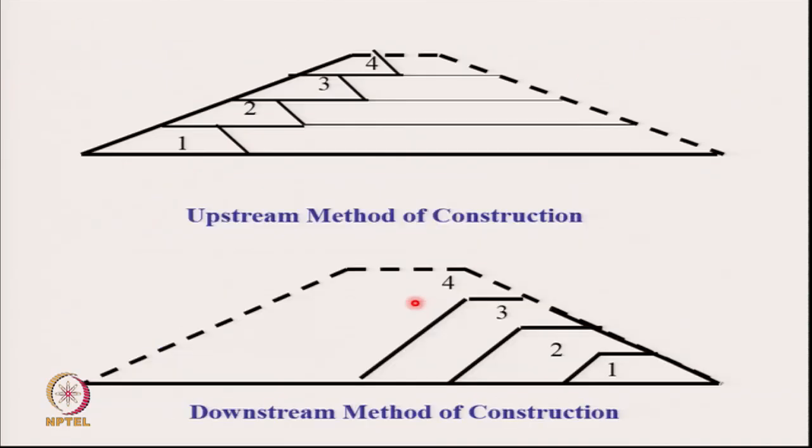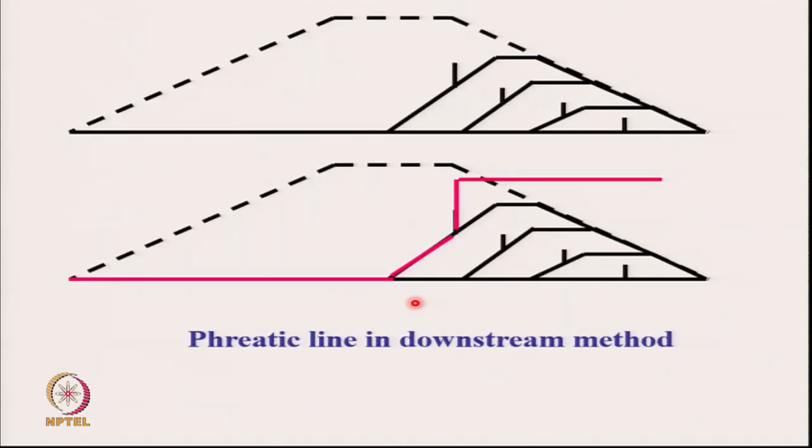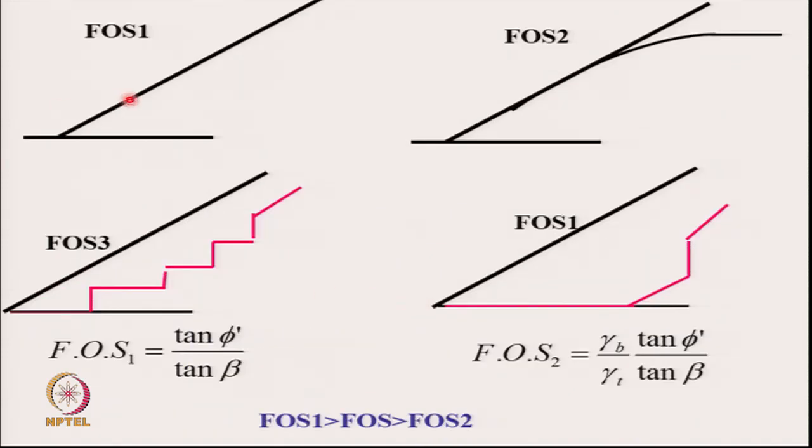When we apply them to ponds, which are finite slopes, I will look at a dry slope with no internal drain, then the phreatic surface will be like this. Here you will see its flow acting downwards. I'll have a formula for this and I'll have a formula for this. And when I put internal drains, this phreatic surface will go backwards. So do remember that our factor of safety is between the dry case and the flow parallel case.